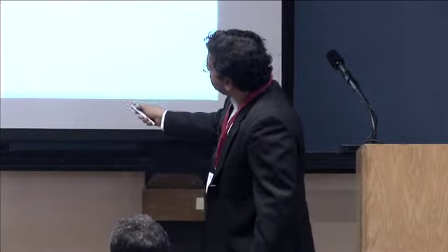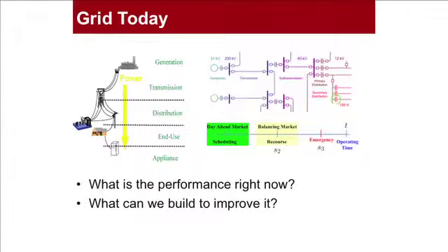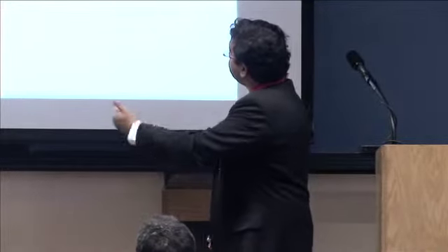So first you run a day-ahead market where everybody comes in and says, what I want, what you may offer. So we all come and propose that. We say, okay, from your offers, I will take these particular generators, and users, I'm going to charge you this much for that generation. Then on the next day, maybe an hour before the time of delivery. So this market is run for every hour of the day. So from 8 to 9, 9 to 10, 10 to 11. So let's say we are selling now for 8 in the morning to 9 in the morning tomorrow.